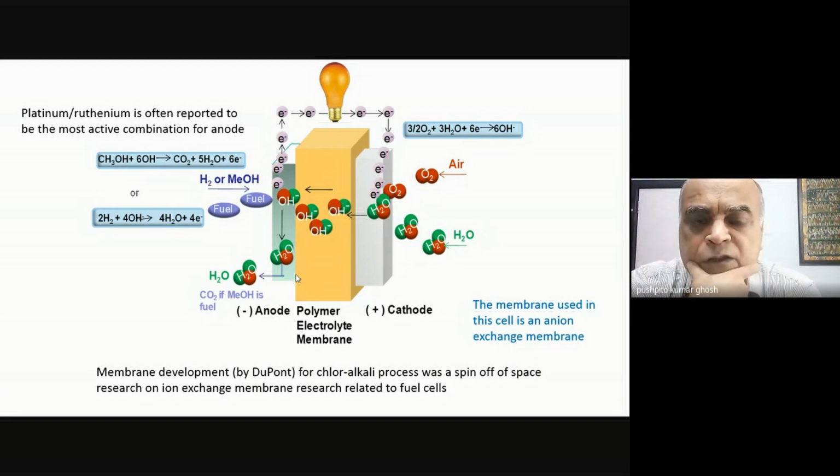Second is that, you see, in the chlor-alkali cell, it's a far more complicated problem than, let's say, this fuel cell. Why? Can someone tell me why? What's the complication? What is something that can be quite destructive if you're not careful? The chlorine. Okay? Because you're forming chlorine. And you know how reactive chlorine is. I mean, it will just chew up these membranes. Okay, it won't survive.